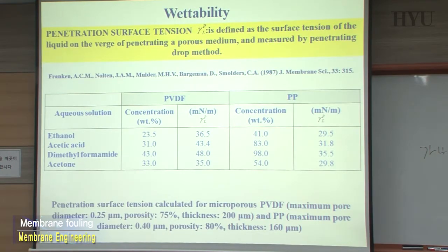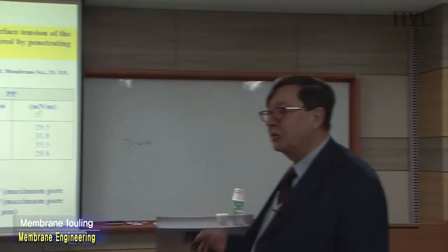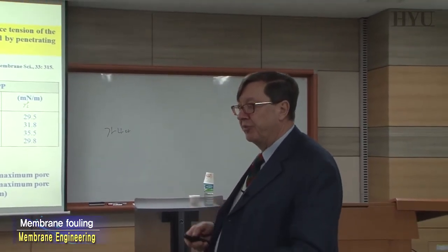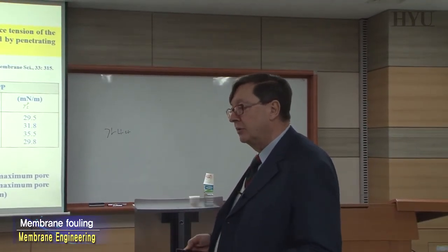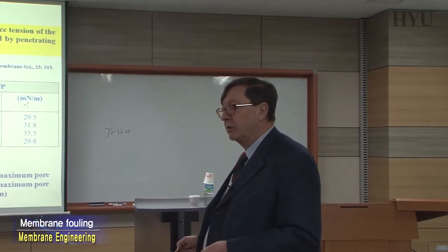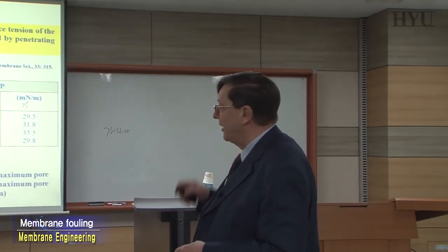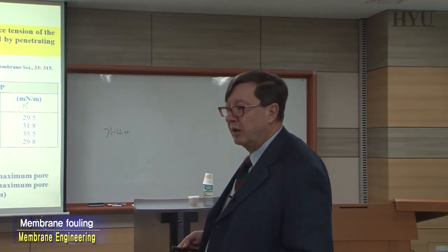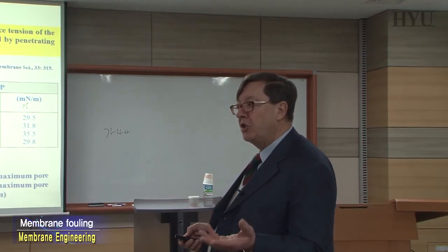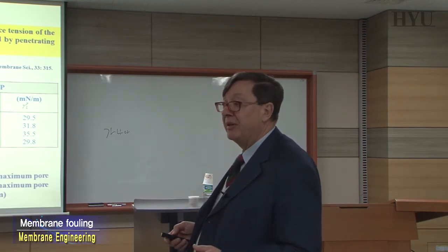Just to mention, before closing, that until now we have been discussing what we can call the traditional form of fouling. Fouling that people have been studying for a long time on ultrafiltration, reverse osmosis, nanofiltration membranes. But today we are learning and studying new kinds of fouling. Some of your colleagues today are studying not fouling related to chemical deposition, cake formation, etc., but they are looking, for example, at change of chemical properties. We will discuss in the next lectures, for example, membrane distillation.